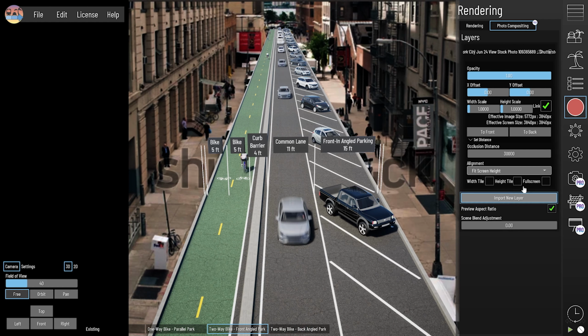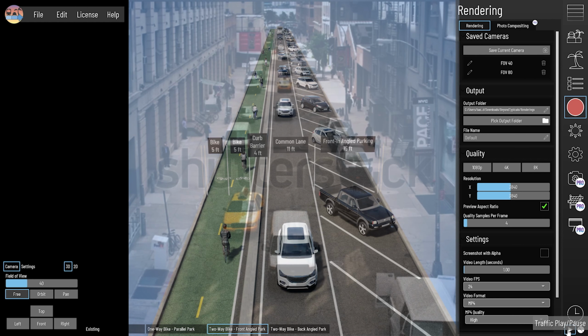As a rule of thumb, to fix your field of view, I'd advise you to look at the far end of the modeled roadway. If you need the roadway to get skinnier in the back, you should increase your field of view. Alternatively, if the road looks too narrow, decrease the field of view to widen out the back end of the road.